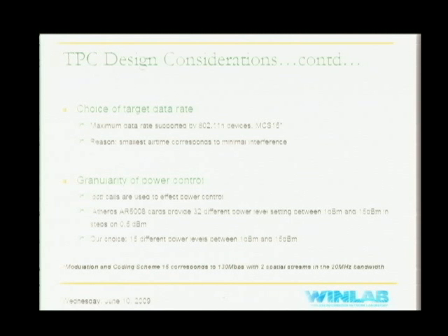So that's what the target data rate means. And it's MCS 15. By MCS 15, what we mean is modulation and coding scheme 15. It corresponds to 64 QAM and 5/6 convolutional code rate. It gives 130 Mbps with 2 spatial streams because the 802.11n devices which we used had 2x2 MIMO. So the maximum data rate that was possible was 130 Mbps in the regular 20 MHz band.